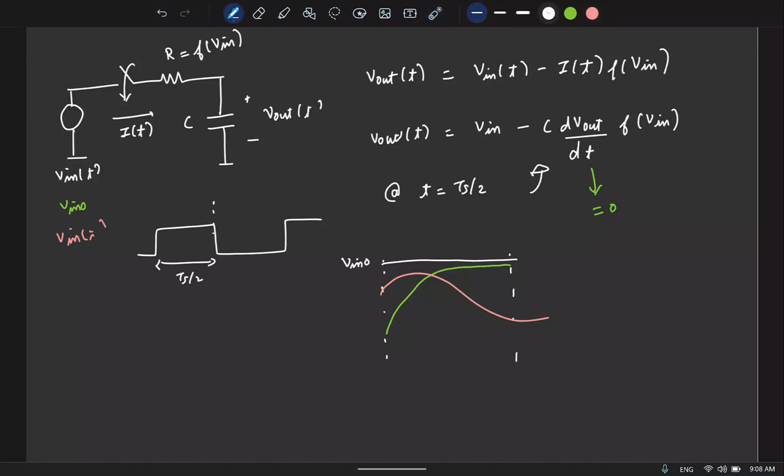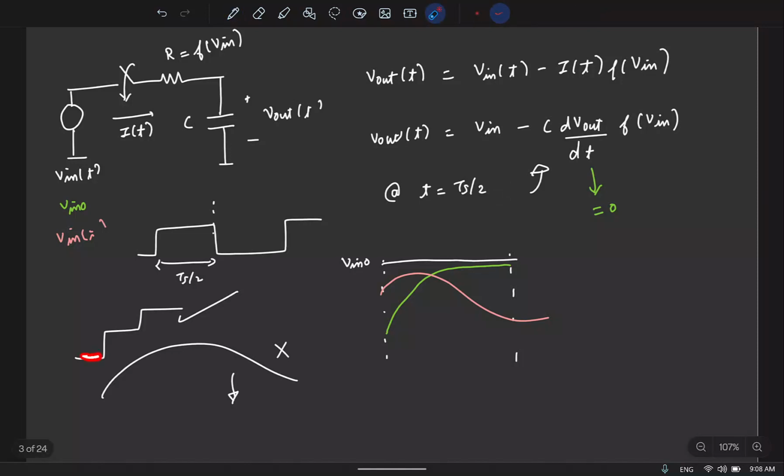So with the CMOS switch, we can either have some kind of held signal like this or a continuously varying signal. So it is okay to use a CMOS switch in these cases, not for these cases. I mean, in this case, you will not have a lot of nonlinearity, that's all. So the bottom line is, if you have an NMOS switch, use it for constant signals close to 0, PMOS close to VDD. CMOS switch can support the entire range, but it is a good switch for these kind of held signals.